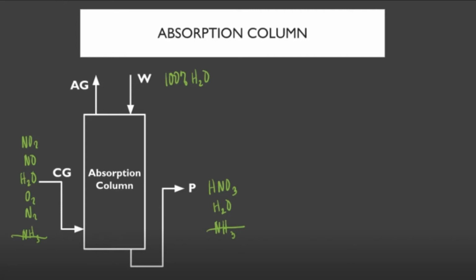Finally, for our absorber gas, we can deduce its components by determining the main reaction happening in the absorption column. For the absorption process, we take nitrogen dioxide, or NO2, combine it with water, and then we form nitric acid, plus a byproduct NO. The byproduct NO, or nitrogen monoxide, can be recycled back to the converter in order for it to be turned back again to nitrogen dioxide.